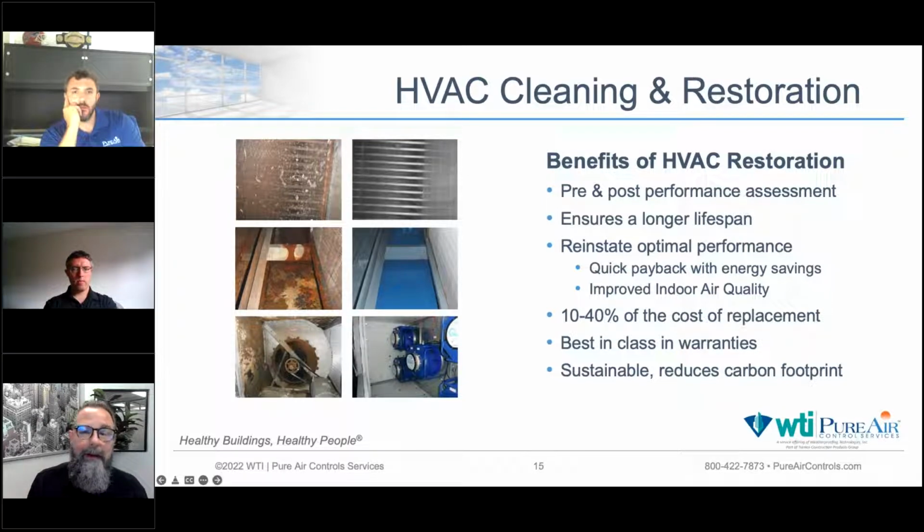And what we have found, and there are plenty of case studies and white papers on our website, pureaircontrols.com, that talk to this, is that we see a fairly quick payback with energy savings just from cleaning the coils with our steam coil cleaning method. It's not uncommon that we would see a 1 1/4 year payback on some of these heavily impacted coils, ones that we're getting 30, 45% better airflow through.